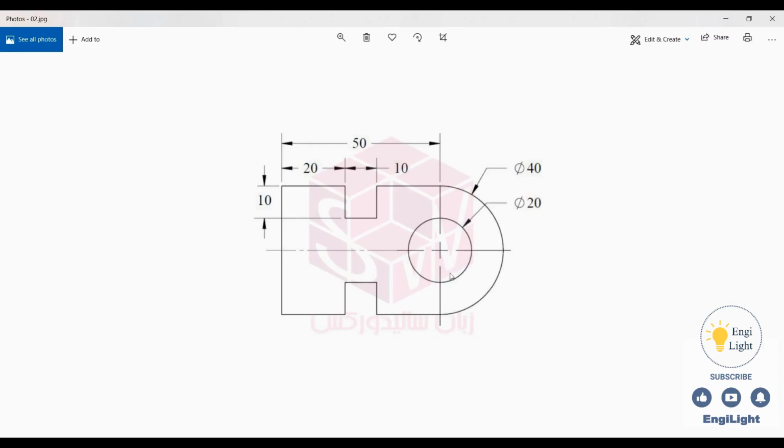As we mentioned, to create this sketch, we first need to define the position of the origin. Where to place the origin is something you'll learn through experience, but there are some tips to follow. First, it's best to place the origin on the sketch's symmetry line, such as this line. Second, it's best to place the origin where you want to start creating the sketch. For example, I wouldn't place the origin here if I want to start by drawing this circle. So in this sketch, I place the origin here.